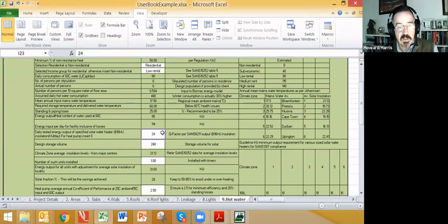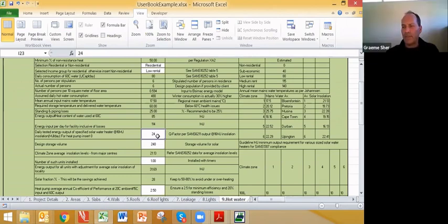The matching figure, Graham, in Cape Town, you wouldn't go over 24 megajoules, I believe, in your experience. As a rule of thumb, you generally have the output power as a figure of 10% of the liters of storage, and that's a good rule of thumb. We find generally if you increase it, there is a chance of burning out the geyser in summer.